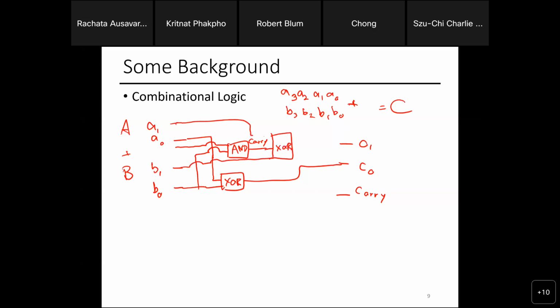All right, this is gonna look ugly because I didn't plan for where the diagram would go. Now we have C0 and C1, right? What's the last thing that we need? The carry. How do I do the carry? Because it's not as simple as an AND. So basically it's A1 and B1, or A1 and carry, or B1 and carry. I just need 2 of the 1 from all my 3 inputs, right? My input is the A and B and the carry.